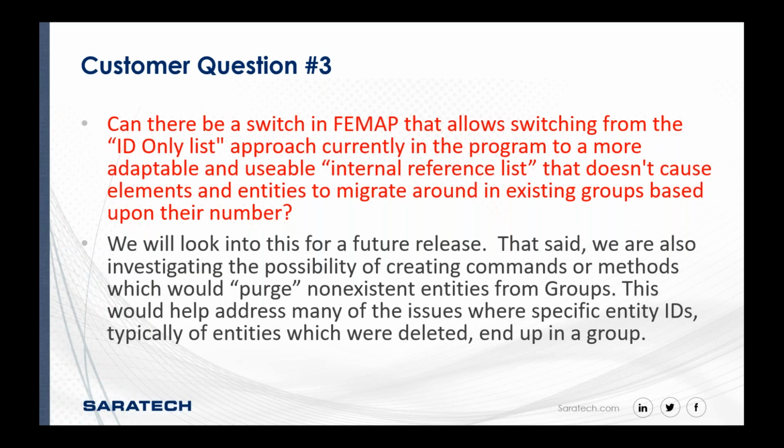Part of the reason we do groups this way is so you could set up your groups ahead of time, because a lot of analysts use just sections of IDs for certain portions of their structure. So essentially you could say, from, say, IDs 1 to 10,000, that's just going to be this one section of your model.